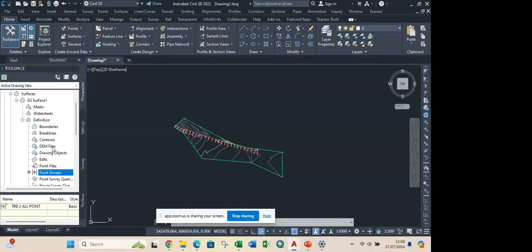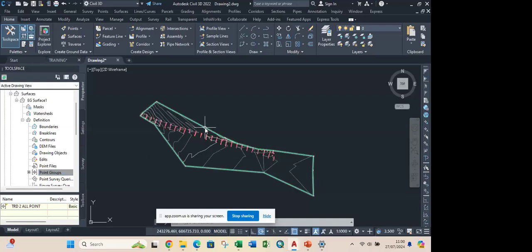That one is done for preliminary listing, but in real sense, the surveyor needs to go to the site and do a detailed topographic survey. Because if you trace with Google Earth and do it, you can't have the actual elevation of the road. Once you go for setting out, there will be errors in your cut and fill. So basically, this is how you create your surface.